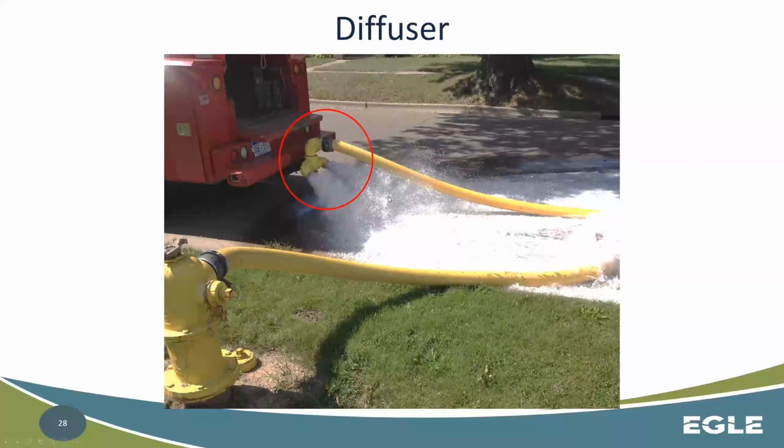This is a really good example of a setup that they've built themselves. I think this was the city of Portland, if I'm recalling right. They had several actual dead end locations in their system, and they would go to those last hydrants in those dead ends and do this flowing, and always saw a continual improvement to customer water quality in those areas every time they would do this. So they just did it routinely.